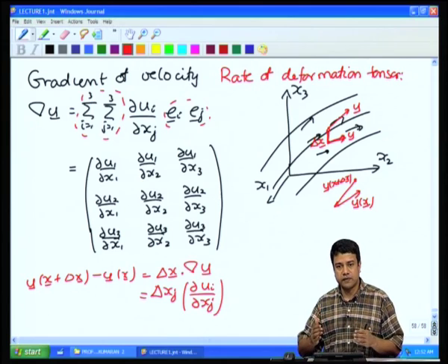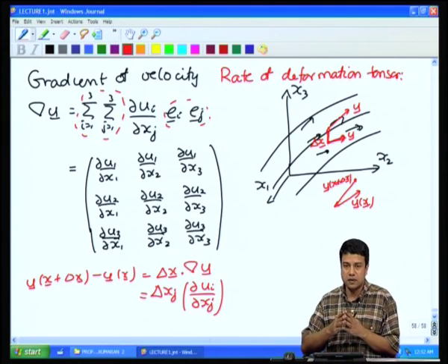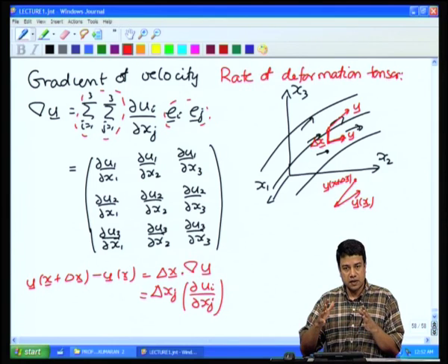In other words, if I was having some fluid flow experiment going on in some container, and I moved that container with a constant velocity, every point within the fluid moves with that exact same velocity. So, there is no deformation taking place, and you require deformation of material elements in order to generate stresses within the fluid. That means that stresses cannot be generated if the entire equipment is moving with a constant velocity.